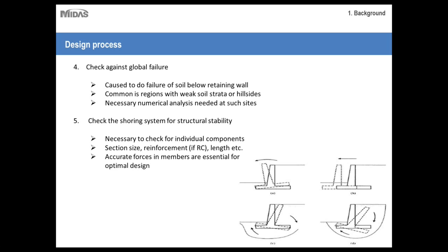And in order to design these shoring components optimally, you must have accurate design forces. This is a very big component of the entire design process. If you don't have accurate forces, you will always end up with oversafe structures, which will not be cost effective.